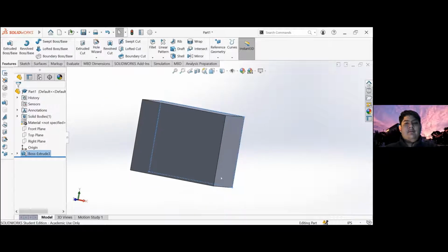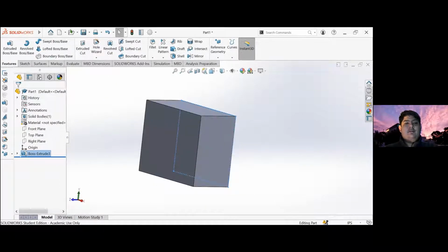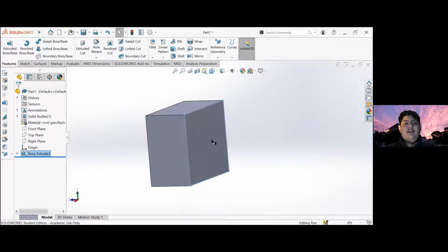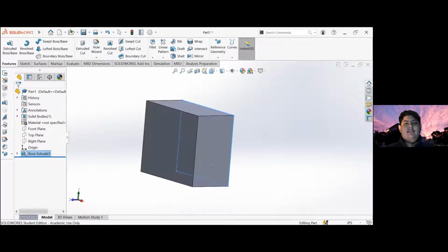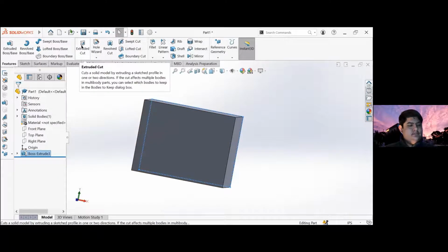So last time what we did with this box is, in our extrusion, we shelled it with thin feature, and we drew kind of a rod going through it. But this time I'm going to show you other features. So the first one we're going to try out is Extrude Cut. Extrude Cut allows you to do exactly what the name says. You can cut into any extrusion. So I'm going to go ahead and select it.